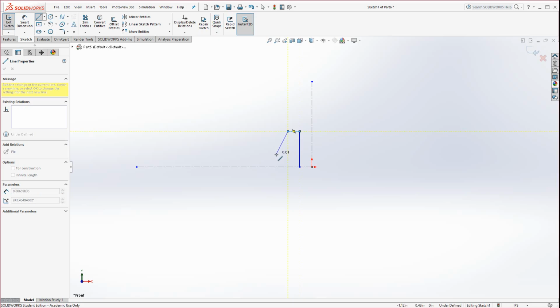Click. Now we're going to draw a little angle in here because there's a taper on that center. And so just draw this out about 1 inch in length. Don't let it contact the horizontal center line. Just glide up above it like I have it. Click again. Now move your pointer to the left about 1 inch. Make sure it's horizontal. Click.